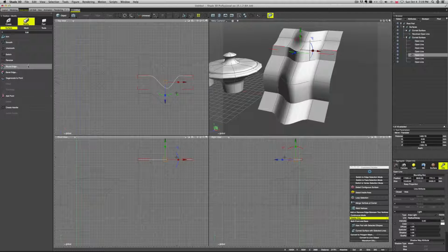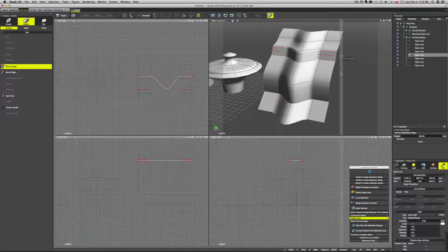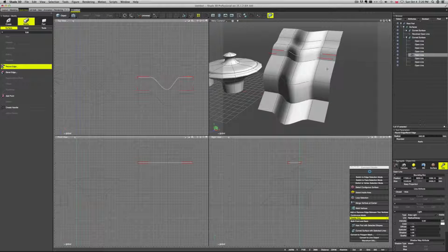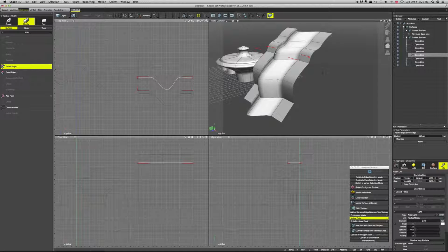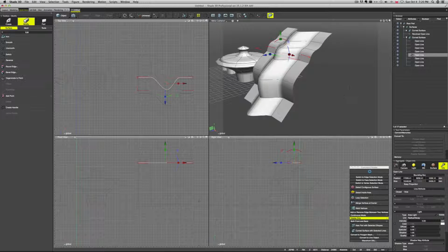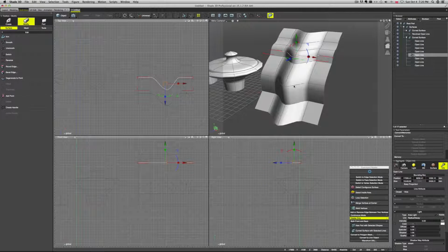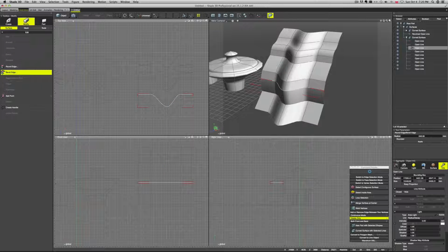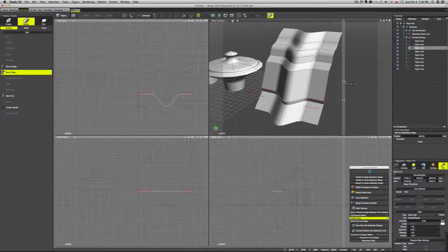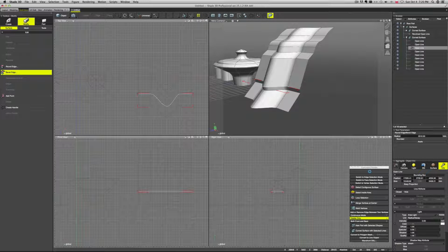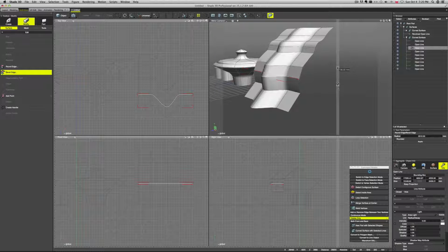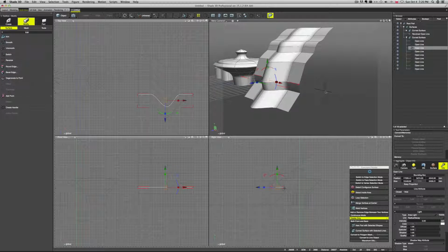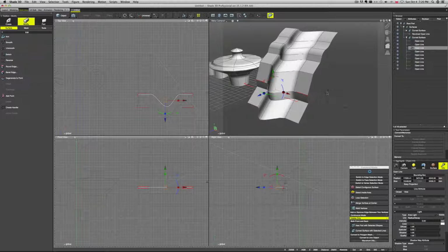Let's, for example, round the edge here. If we select one of the edges, click round edge, and then start dragging across the screen, it will start smoothing it. So this way you can smooth the angle if your object is too angular, for instance, or you can go bevel edge, which acts the same way, but it creates more angular surface, as you can see. This is useful if you want to create some very hard surface looking objects, perhaps.